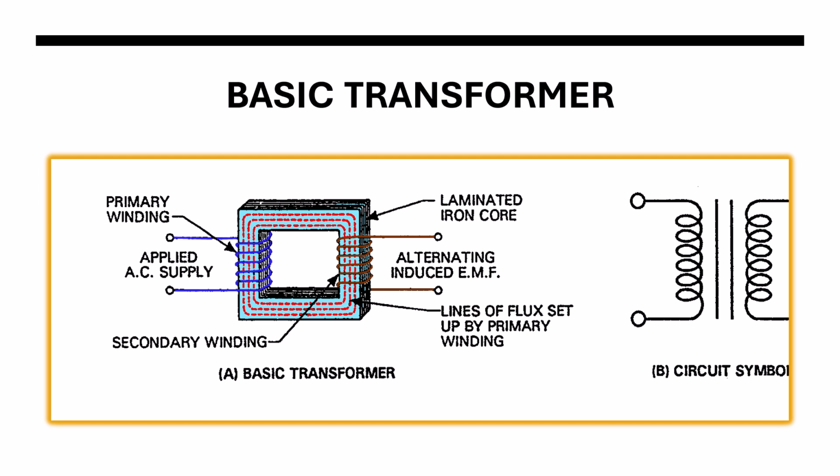The basic principle behind the working of a transformer is the phenomenon of mutual induction between two windings linked by a common magnetic flux. The figure at left shows the simplest form of a transformer. Basically, a transformer consists of two inductive coils, the primary winding and the secondary winding. The coils are electrically separated but magnetically linked to each other.